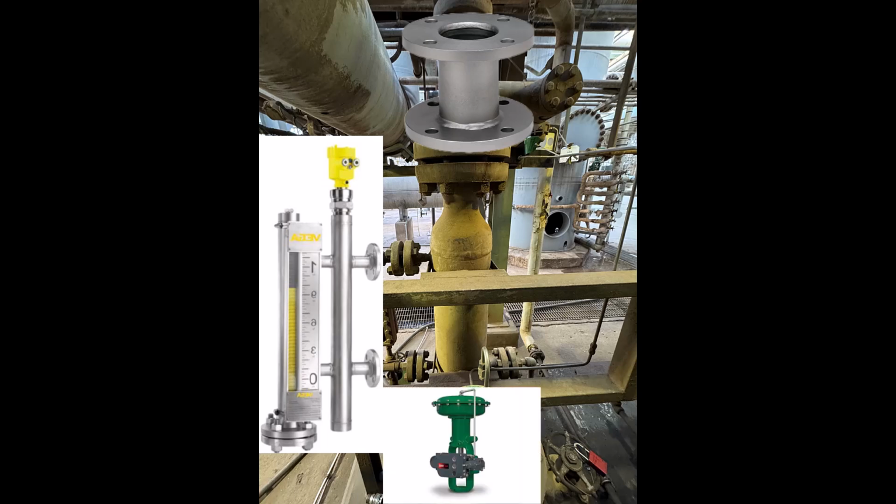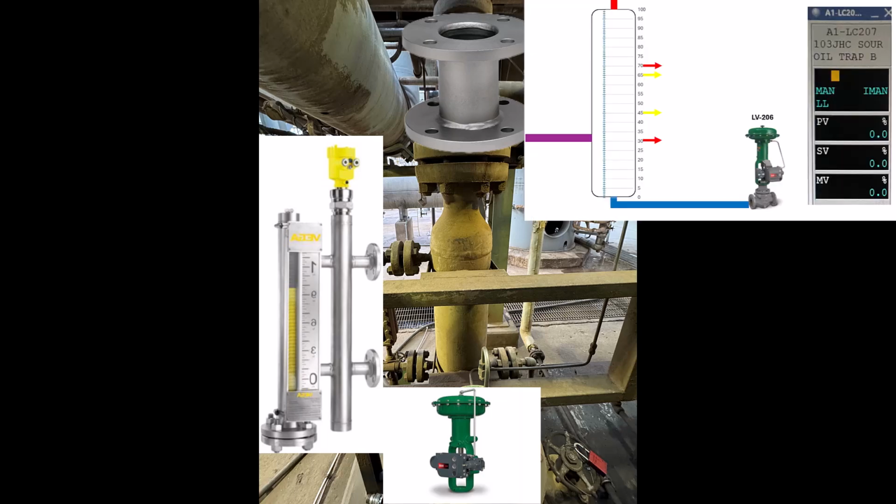The actuators and positioners on both LV206 and LV207 will be replaced with new upgraded digital style equipment. The system and its data will now be run into and from the DCS system, where before it was all local control. There is new logic to how the level controllers will operate in an abnormal manual mode that cannot be manipulated by the console operators.